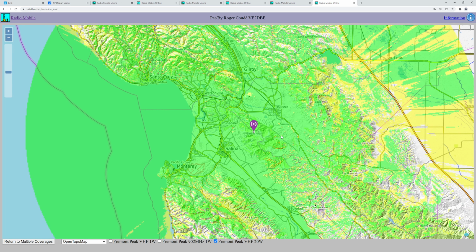The other thing I'd like to point out while we're on this software is that this is a little bit optimistic, if you will. I've often found that plotting with the default values is a little bit optimistic for actual radio performance, especially since I'm often doing event support and calculating where to put repeaters for a temporary deployment. Typically you have handheld radio users that might not have high gain antennas. They're less trained operators, or they're not setting up a big base station. So often what I'll do is drop that power number significantly.